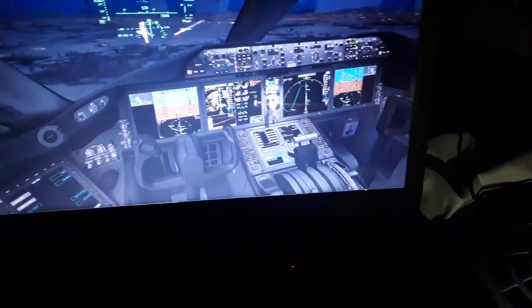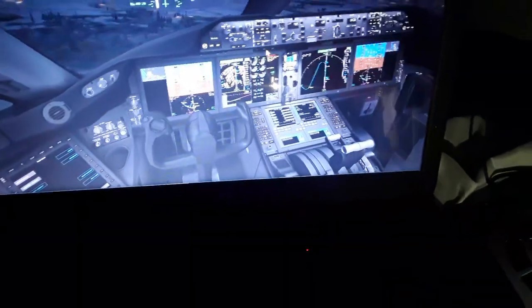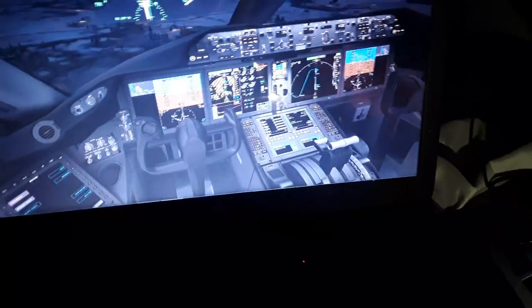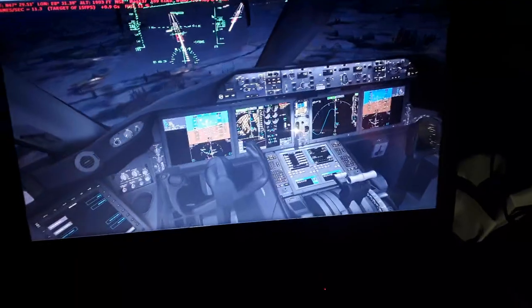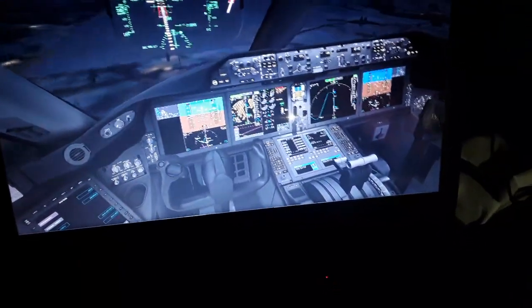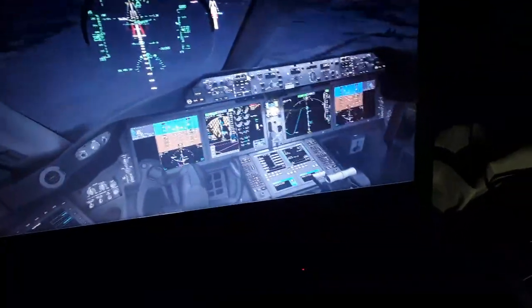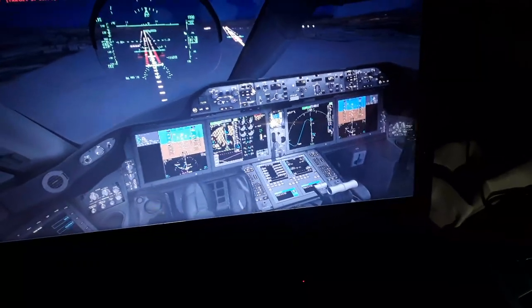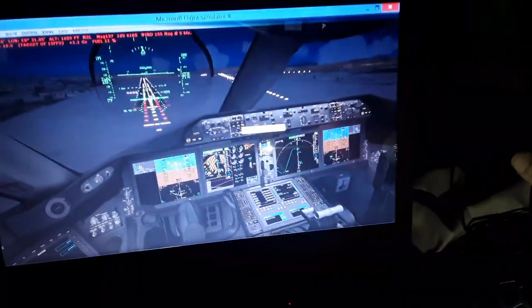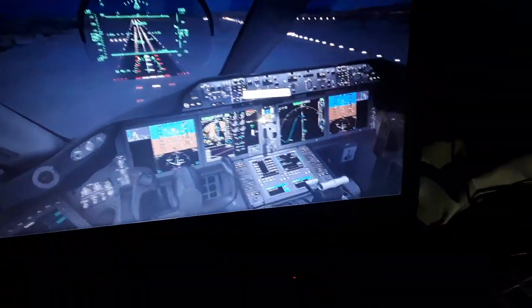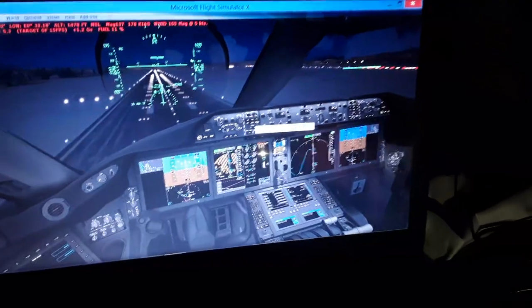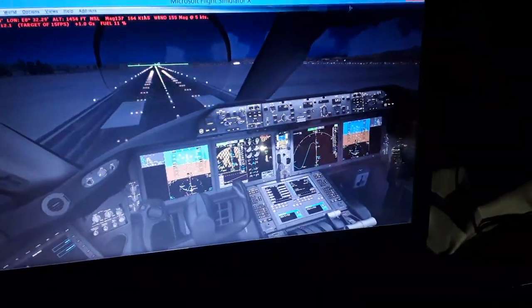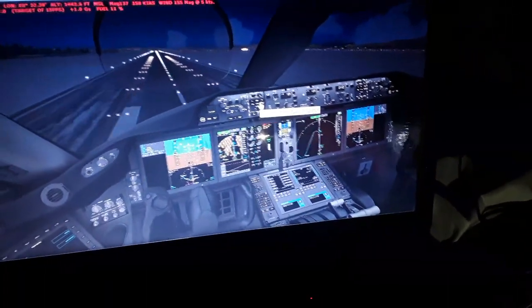I'll do more thrust. And need to increase the rate of descent, align with the rudder pedals and the yoke, the ailerons and the spoilers, and also a little bit less power now. And we're very close here for the flare. So we are approaching the runway. We're gonna flare the aircraft for the touchdown. So we need to align, and here is the flare.